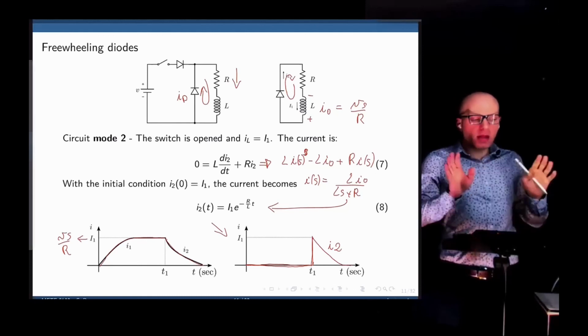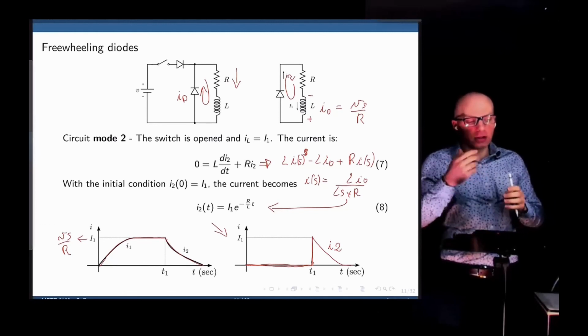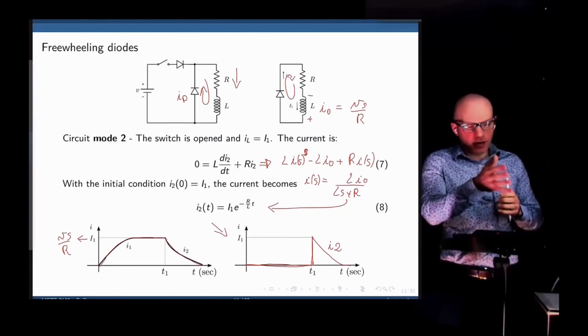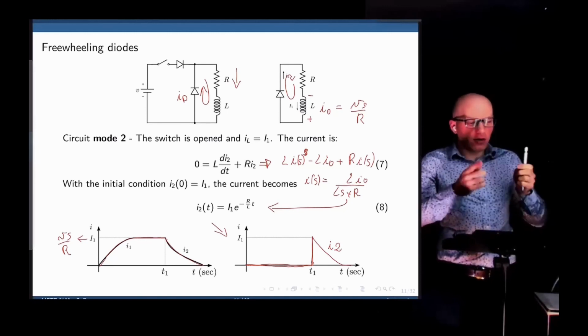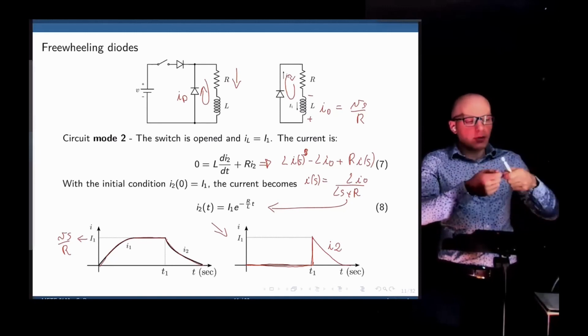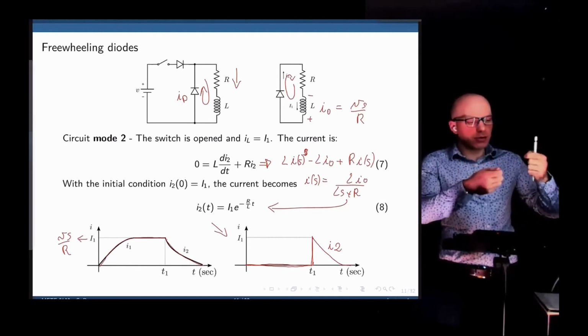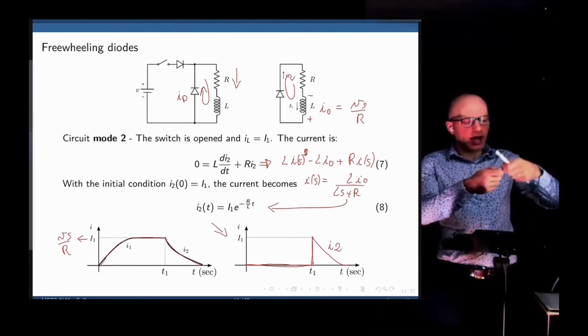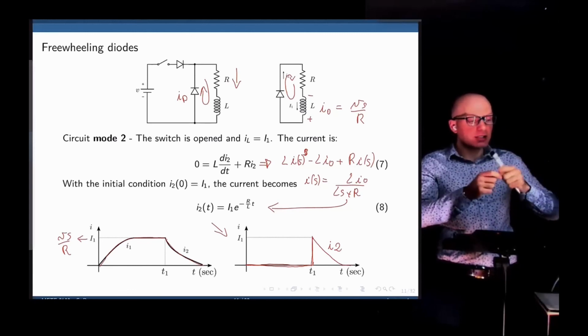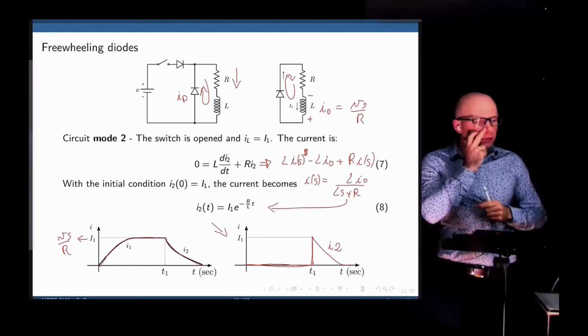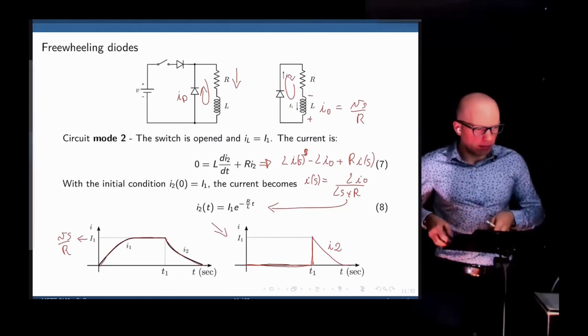If you do any mechatronics project with inductive loads, you must make room for a freewheeling diode. Even if you power on, take like a DC motor and take a wire and just connect it and remove it by hand, you see that there are sparks there. And these sparks are coming from the inductive load. So if you have a freewheeling diode, that should not happen.